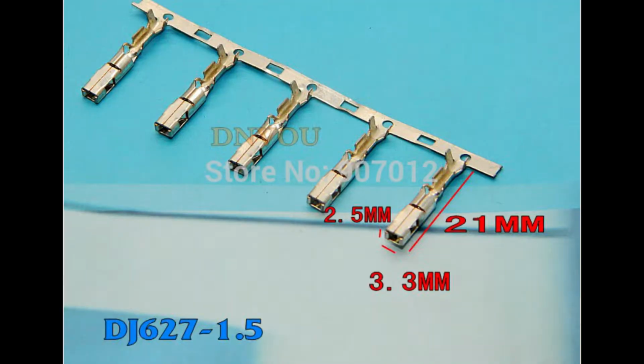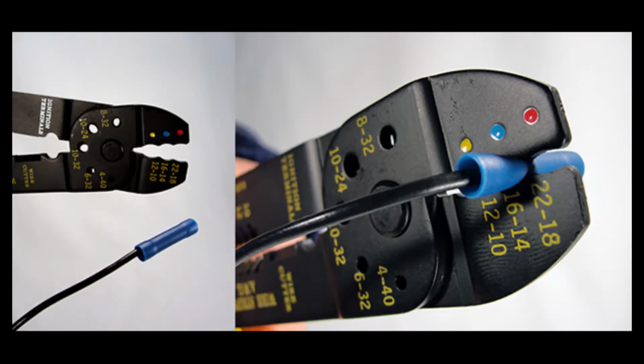So we're going to get into our wire repair by first eliminating the old defective one by either depinning it or cutting it, and then we're going to replace it by either repinning it at the connectors, or if we cut it, we're going to use crimping with butt connectors and heat shrink.